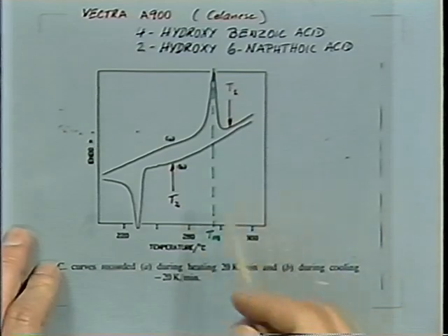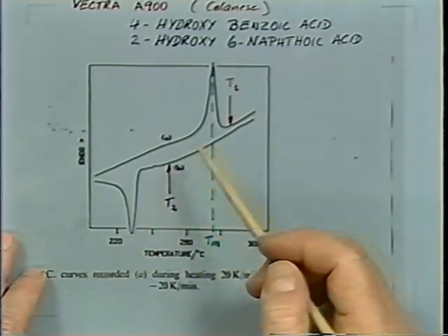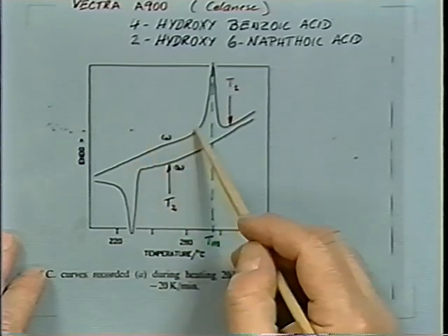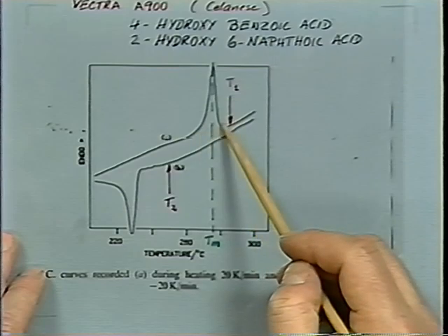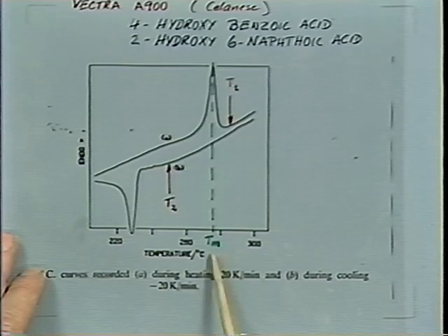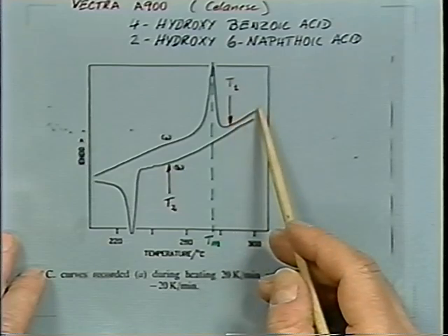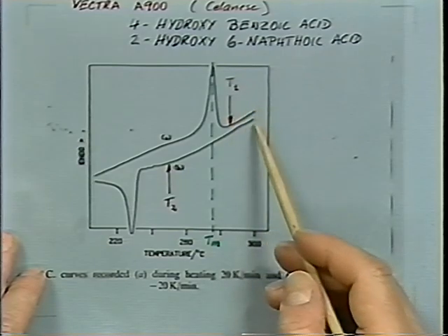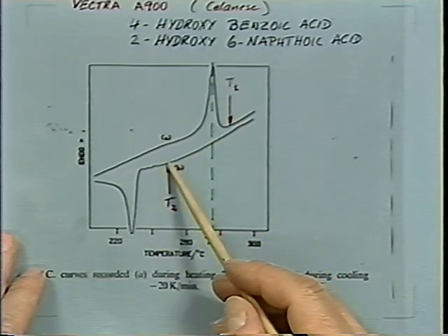When you heat up the sample, that would be the first heating cycle. You do this once or twice. So you heat up the sample. The melting occurs over a very broad temperature range. The temperature of highest melting rate we would call the melting temperature, the nominal melting temperature. And beyond that, the material is a liquid. If you heat further, the melting will be completed, and then during cooling, the material stays a liquid for quite a while. It will stay in a supercooled state.